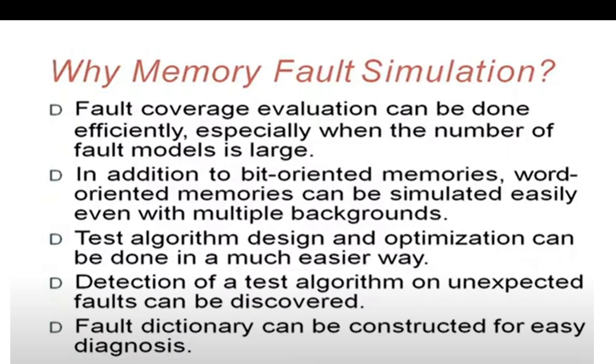Next is why memory fault simulation. Fault coverage evaluation can be done efficiently, especially when the number of fault models is large. In addition to bit-oriented memories, word-oriented memories can be simulated easily, even with multiple backgrounds. Test algorithm design and optimization can be done in a much easier way. Detection of test algorithm on unexpected faults can be discovered. Fault dictionary can be constructed for easy diagnosis.